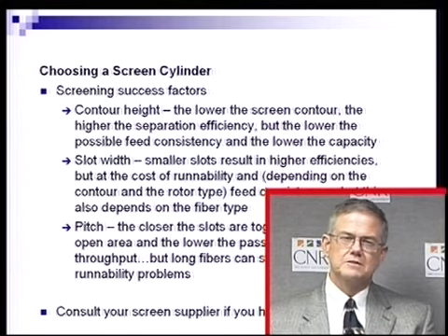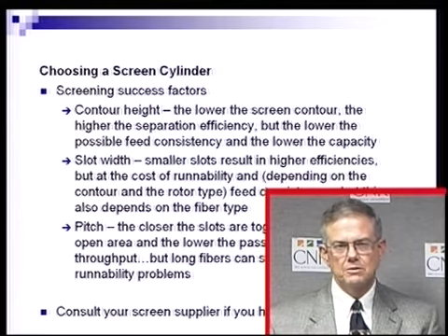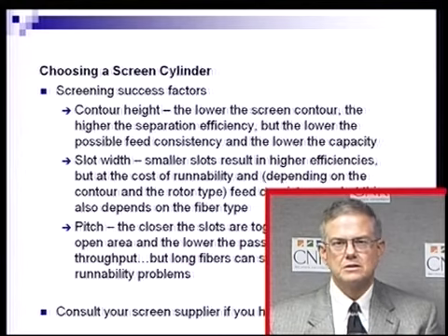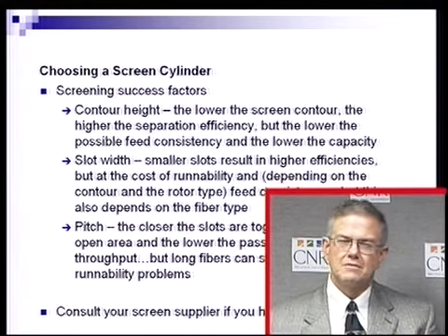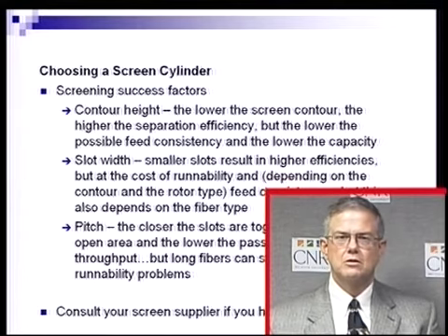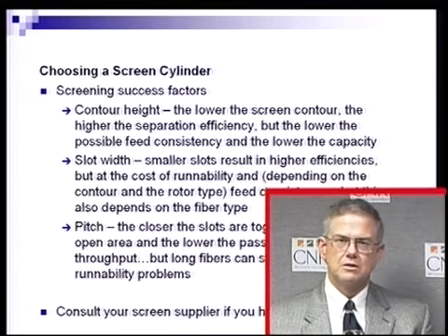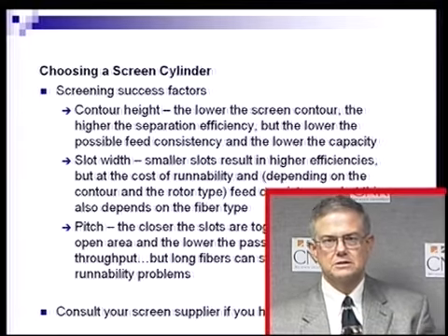The problem is that if we get them too close together, then we have hydraulic interference between one slot and the next and the following slots, and we actually lose capacity by having more slots per inch. So you have to play with this parameter as well, along with the profile depth, along with the slot width and the pitch, in order to get a screen that performs suitably in your installation.